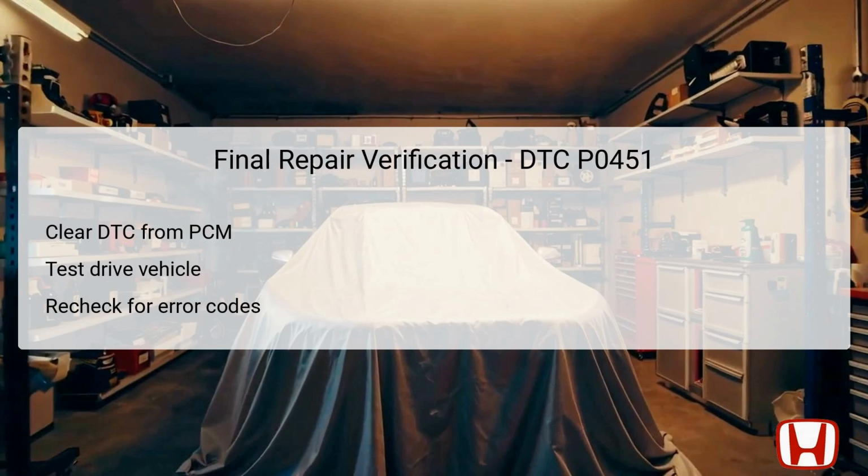Upon completing repairs related to DTC P0451, the next step is final verification of the repairs made. Start by clearing the DTC from the Powertrain Control Module (PCM) using a scan tool, resetting the monitoring systems back to their default state. After clearing the codes, a test drive of the vehicle is necessary to allow the system to re-evaluate its operations and confirm whether the issue has been resolved.